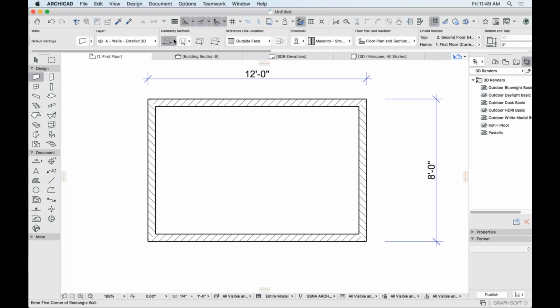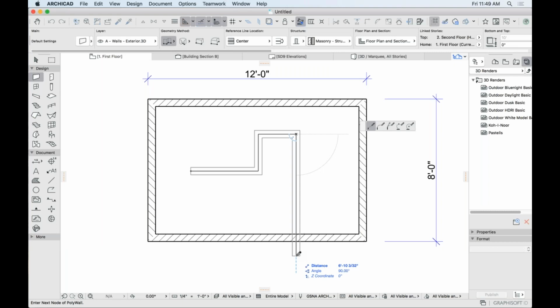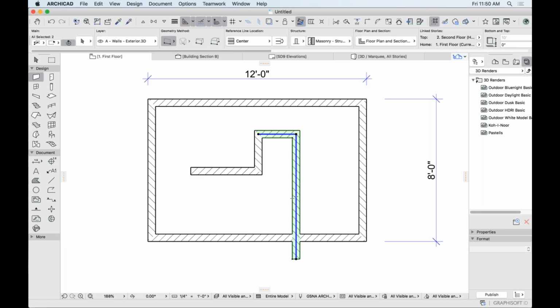So as I'm drawing, let me draw a set of chain walls. If I'm drawing and then all of a sudden I've created 3 walls and I say, oh shoot, I didn't mean to be drawing this on face, I want it to be on center, I tap the C key as I'm drawing, and notice I can toggle through, and I haven't even finished drawing my walls, it just toggles through so that by the time I do click and finish that out, notice that blue line as I select the walls is right down the middle. Okay.